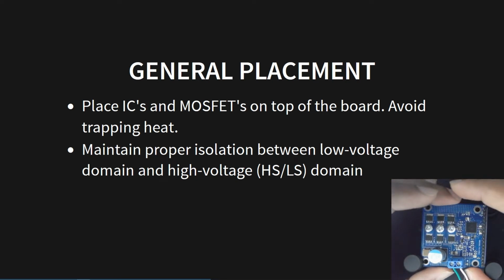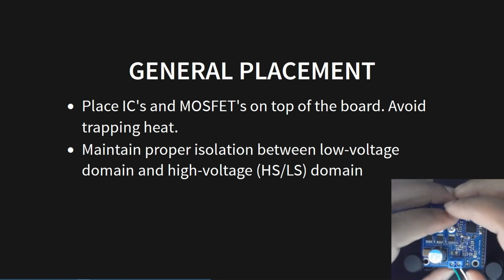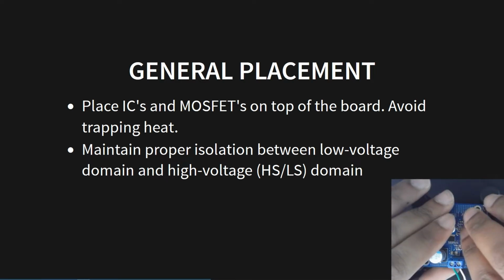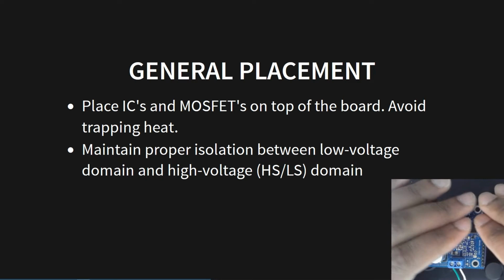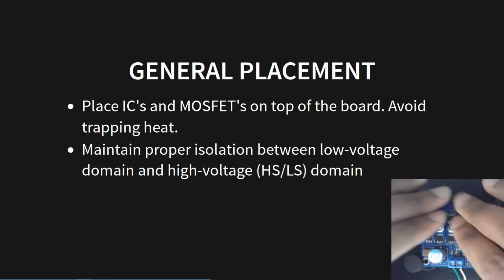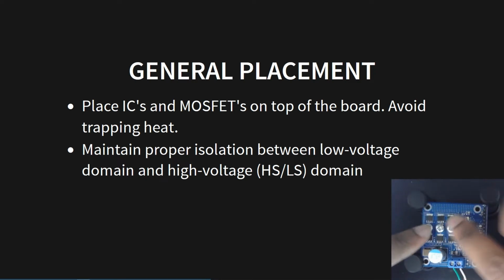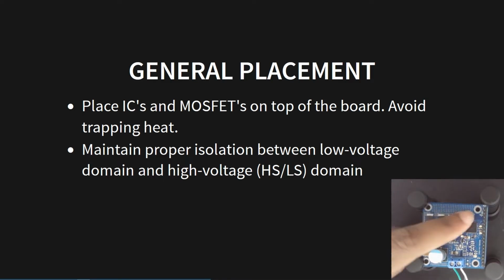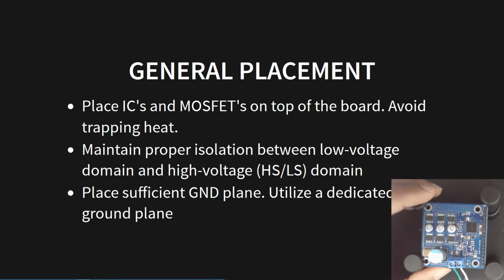Now, I'm not completely researched as to what real proper isolation means, but I could almost certainly think that you want to keep all the low voltage and low signals on one side of the board, and all the high voltage on the other side of the board, which in a nutshell I've actually kind of done in this particular layout as well. I will be talking more about the PCB design of this board shortly through the CAD software. But for now, I'm just giving the general guideline principles, and then from there we will dwell deeper into it.